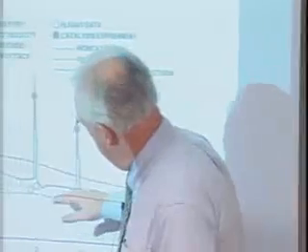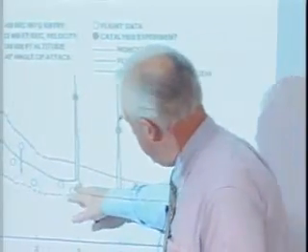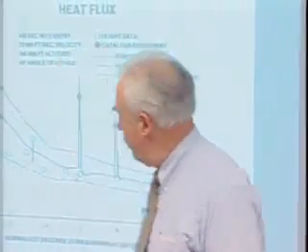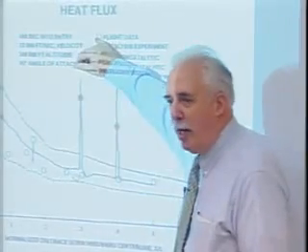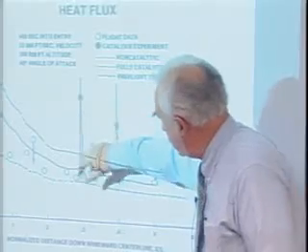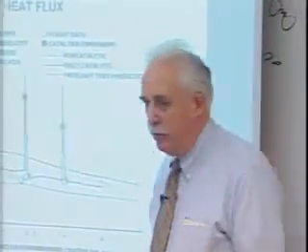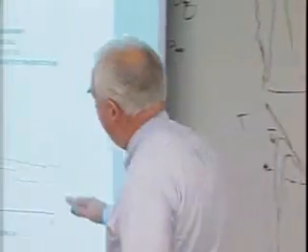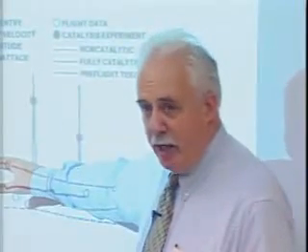If the whole vehicle was like that, the heating would have been up here. But since it was just a tile, a boundary layer comes along here, and all of a sudden, boom, it gets hit with a different boundary condition. Okay, we've got all those atoms, and they see this catalytic surface. The heating goes way up, okay, and then relaxes. This is the computation, and there's the measurement. So indeed, here's a demonstration that chemistry can be important in this flight regime.